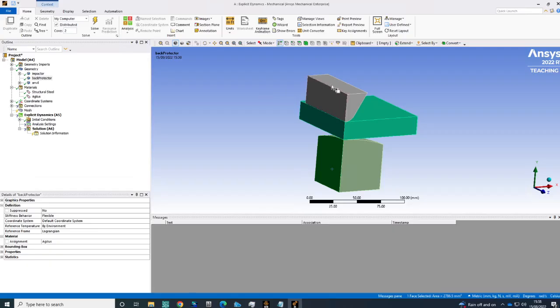Well, this anvil, if I just continue by setting up the simulation, it will use the mass of the quarter of the anvil, which is this, but there is no guarantee that this mass will be a quarter of 5 kilogram. And in reality it is not. I have already measured the mass of the entire anvil and subtracted it from 5 kilogram and divided the resulting value into 4, and now I'm going to apply that quarter mass on this part as a point mass.